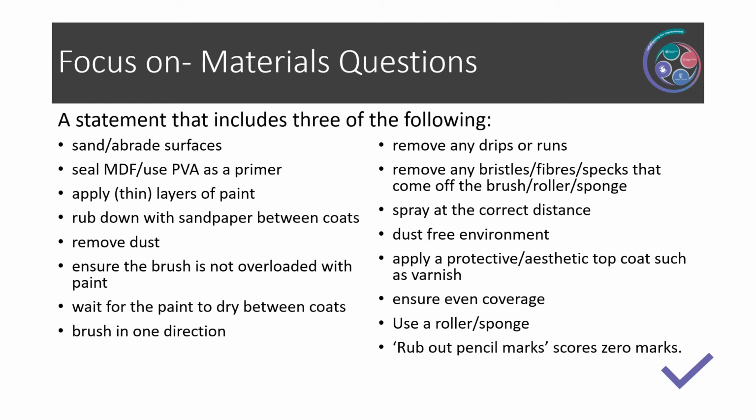Waiting for the paint to dry between coats is an essential step. If you apply a second coat of paint before the first coat of paint is fully dry, it will lift the first coat of paint and leave behind an unwanted texture.